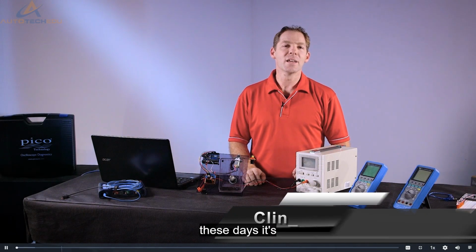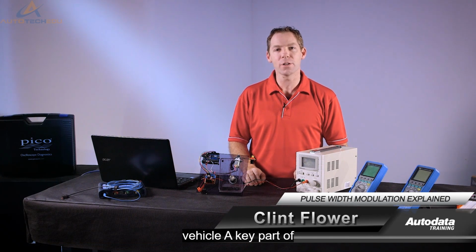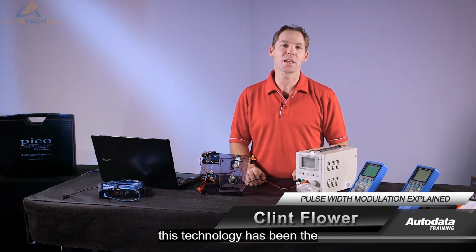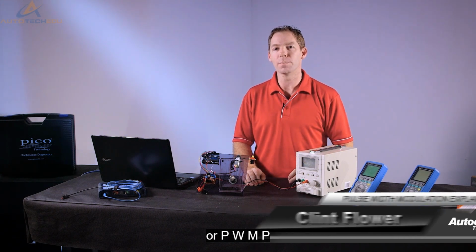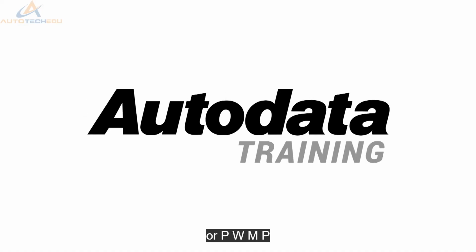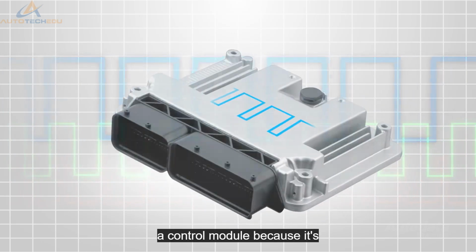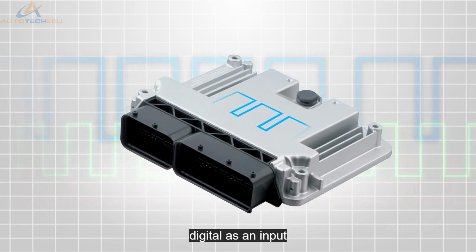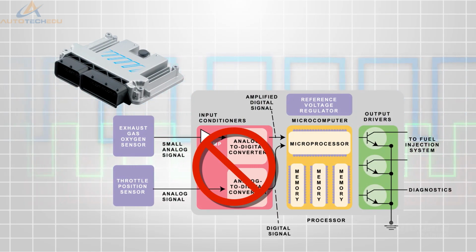These days, it's not surprising to see digital technology incorporated into the modern vehicle. A key part of this technology has been the use of pulse width modulation, or PWM. PWM is perfect as an input or output for a control module because it's digital. As an input, there's no need for an analog to digital converter.